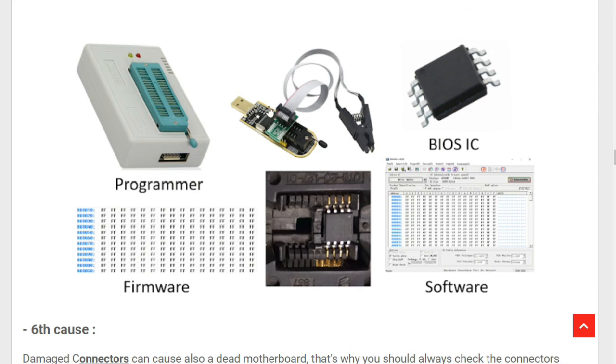This programmer, basically, you can just connect it to the laptop via this USB, as you can see, and then connect this support, as you can see here, directly to the motherboard without desoldering the BIOS, and then you can program it directly from the motherboard.